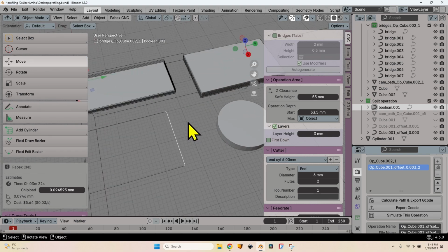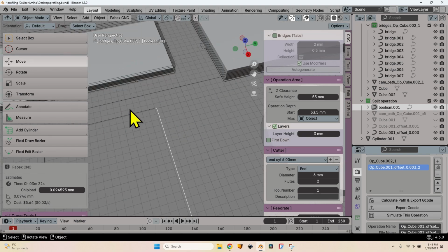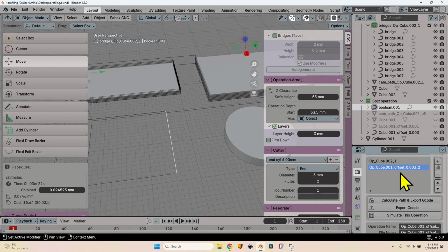curve, the one surrounding the object, split into two perfectly matching objects because I used difference, a boolean, not manually trying to modify the points or anything like this. And now I will just copy the operation for these three edges. Click on the copy operation button here.